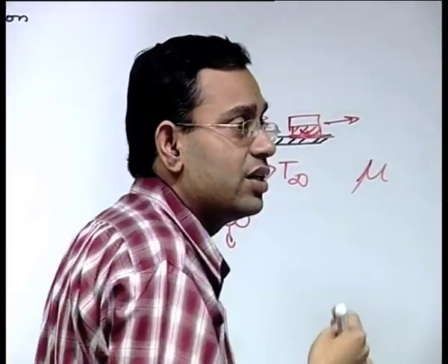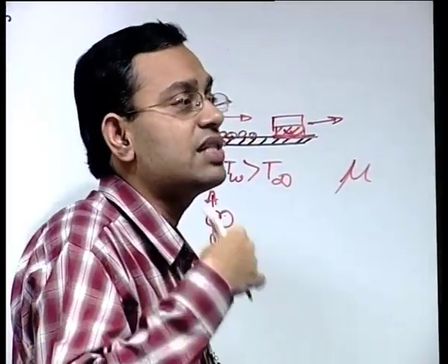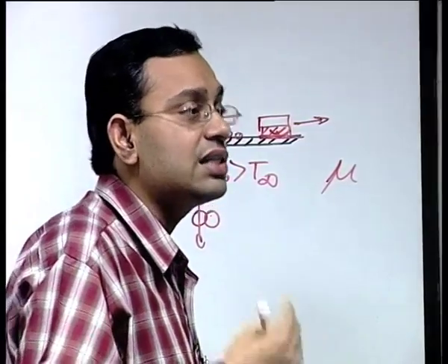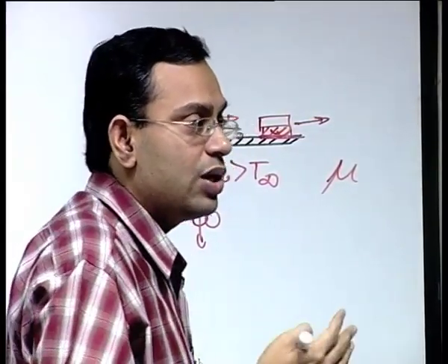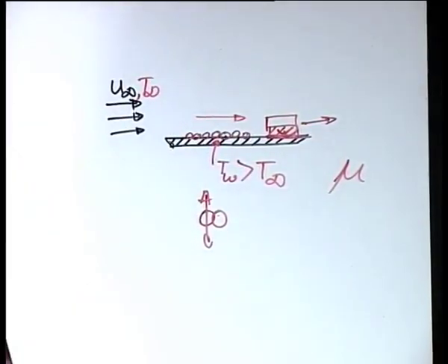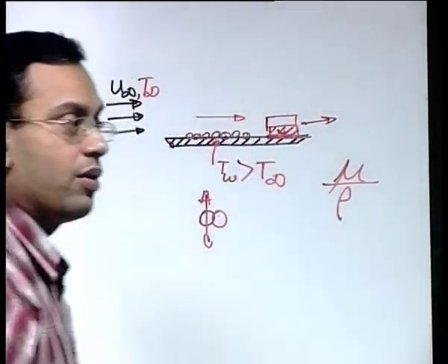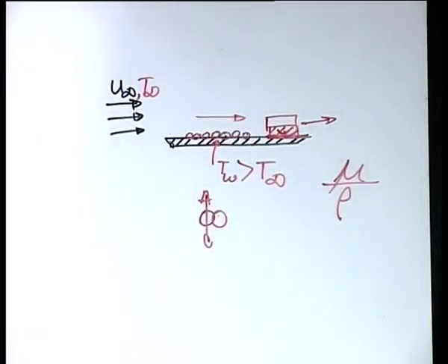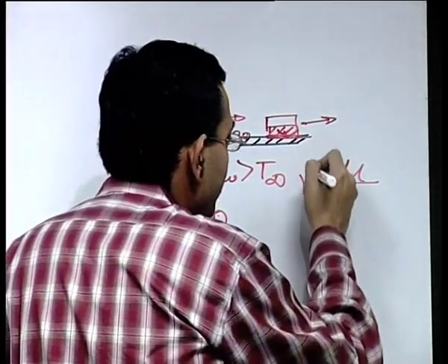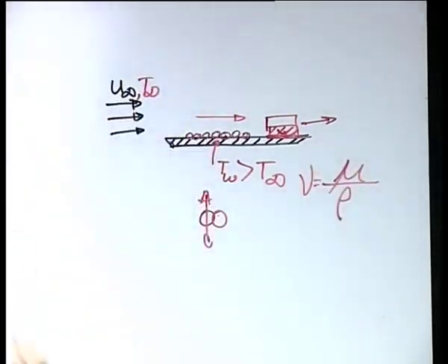So, viscosity is related to a disturbance in momentum. There is something which is an indicator of the sustenance of its momentum, and that is the density of the fluid, because density of the fluid is an indicator of the mass of the fluid element, which is a measure of the inertia of the fluid. So, it is the viscosity relative to the density that is important, not the viscosity alone, which we call kinematic viscosity. This is also interpreted as a momentum diffusivity.